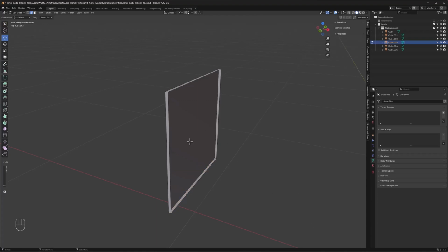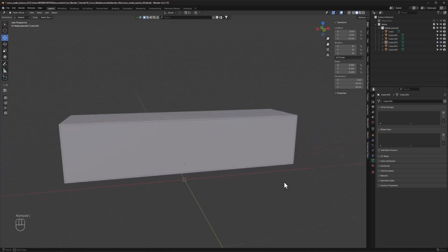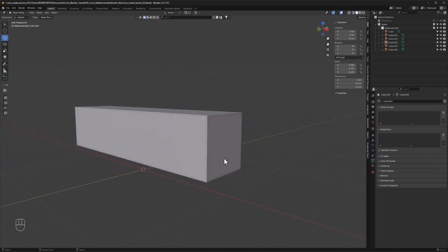As for creating the third face, we can use the same technique we used to create the missing faces of the top and bottom panels. Because by creating the second face, we have effectively connected the remaining edges to each other. So, while holding down the Alt key, click on any of these edges to perform a loop selection, then, using the F key, insert the corresponding face. Switch the display mode to object mode and press the slash key. Select the right vertical side panel.